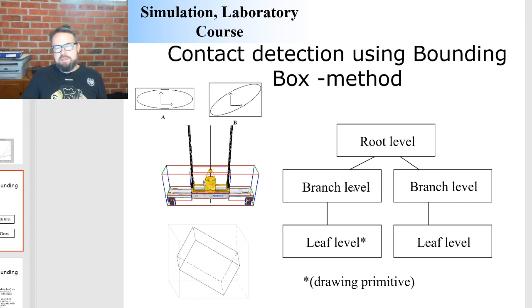And the branch level boxes, like you pretty much guessed already, are much smaller boxes, such that there may be a box under this particular flap that is used to do the connection itself. There may be another box, like the one shown here, which looks at whether this particular part of the connecting device is under connection or is contacting other bodies. So then how it goes is that you see the root level boxes are penetrating, so there is a collision between the root level boxes.